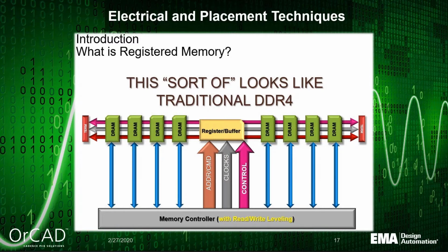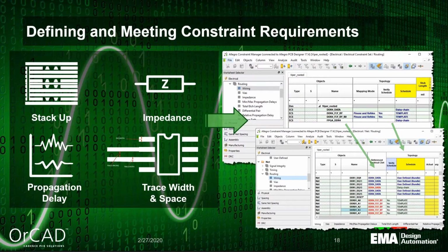So placement is no longer just drop them down and hook them up. The physical design engineer needs to know what the components are, their function in the circuit for placement and routing to achieve this first pass success we talk about. Constraints must be defined and managed.